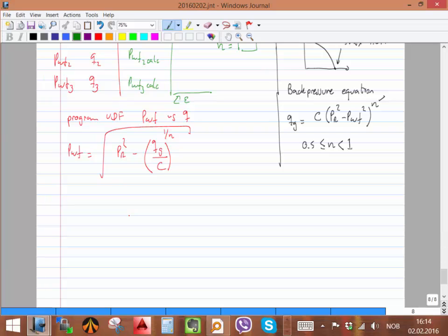Another comment is that this equation is usually done for the preferred phase, the phase that you are producing mostly. And the other rates or the other points, for example, you have your IPR for oil, and the others are calculated just with the GOR or the water cut, just a multiplier. That will be just Q gas is equal to GOR times Q of the oil, right?